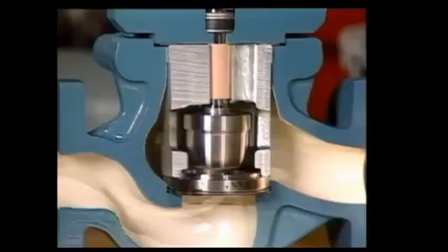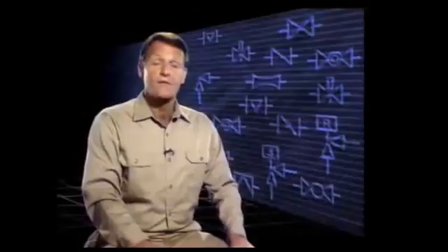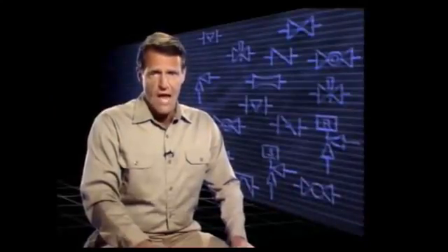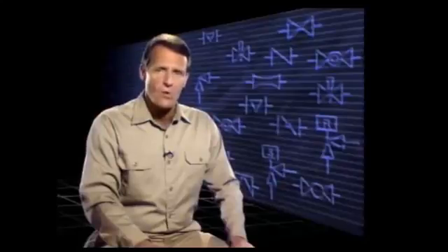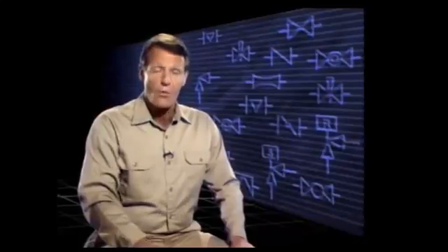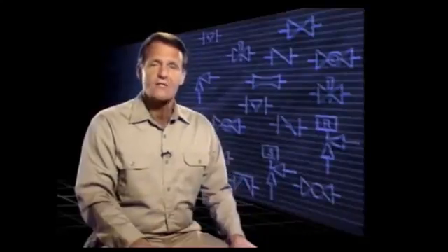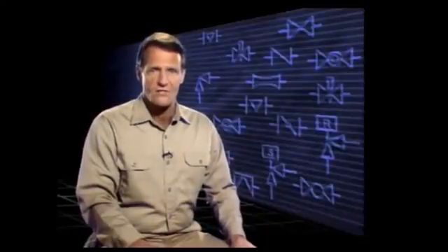The cage is a hollow cylinder containing openings. When the valve disc is moved away from the seat, fluid flows up through the seat, through the cage openings, and out of the valve. In this topic, we discussed general classifications of actuators and what type of power each actuator uses to move a valve. We also looked at the function and design of control valves. Now let's stop and try some practice questions.